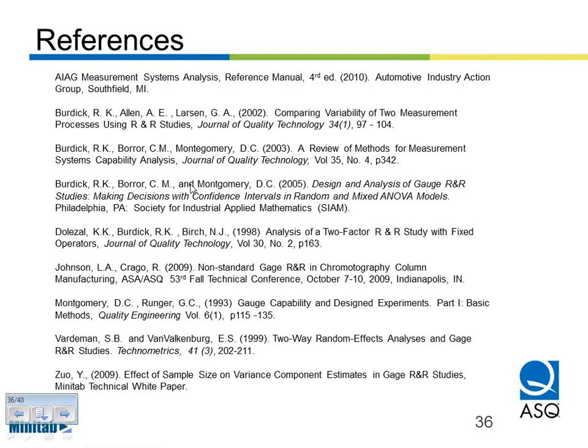When your repeatability is excellent, that means the statistical significance of a smaller interaction effect is more likely. I agree that statistically it will pop up with a low p-value more often in that scenario. But again, I look at a Gage R&R as more of a descriptive study where you're looking for the big hitters. You're kind of doing a Pareto analysis, and the interaction doesn't turn out to be a big hitter, even though it is statistically significant.